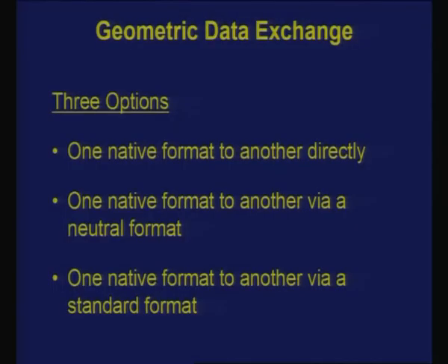These are usually quite fast, this kind of a system, and sometimes they are more reliable, but they are sometimes more expensive too, either to develop or to buy. The other option which we have is to go from one native format to another via a neutral format. Like, a part is modeled in one of the packages, which also has a neutral format, so you can store it as a neutral format, and you write an interpreter which reads this neutral format and writes an output as a native or another neutral format.